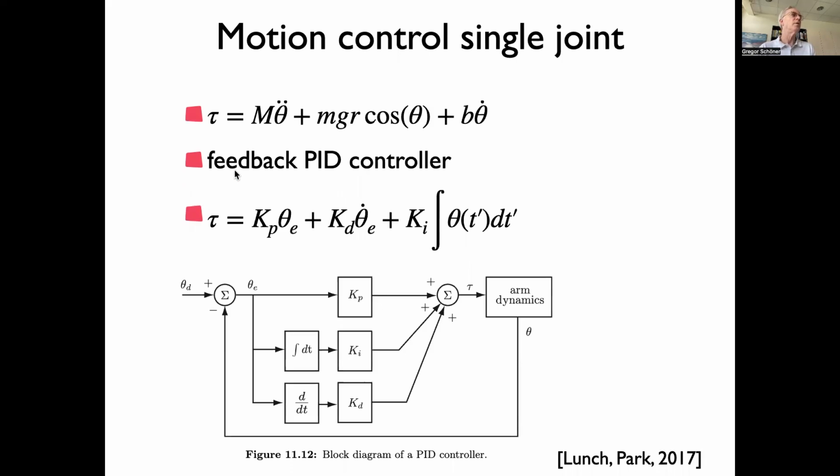And so the simplest way of doing that is to have a linear controller. A linear controller would mean that you make the torque a linear function of the error itself, the rate of change of the error, or the integral over the error. So the P is for proportional control. That is, the larger your deviation, the more you create a torque that goes in the opposite direction. It will be this kind of line here, right? You have a computed deviation, and then proportional to that deviation, you're going in the correct direction.